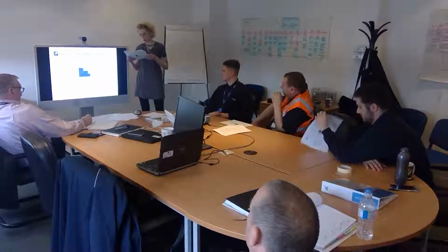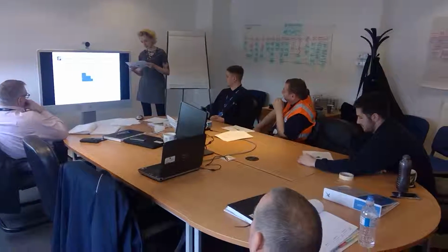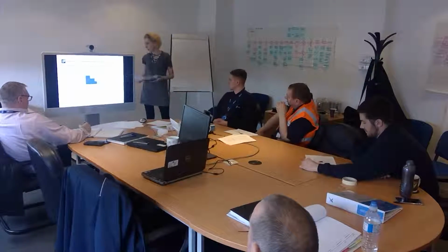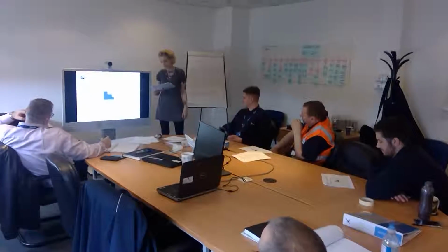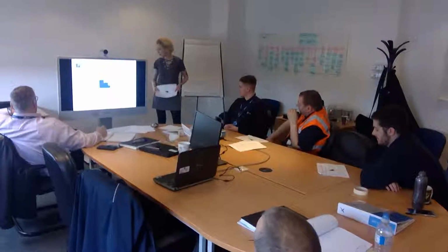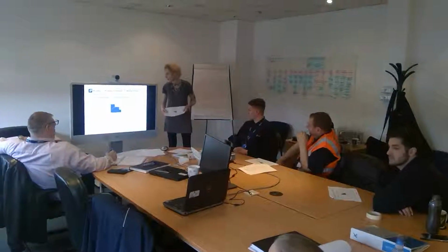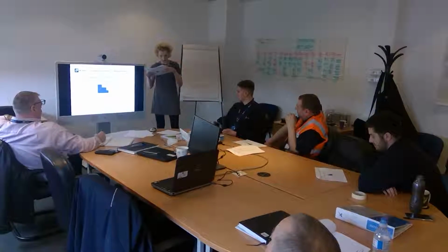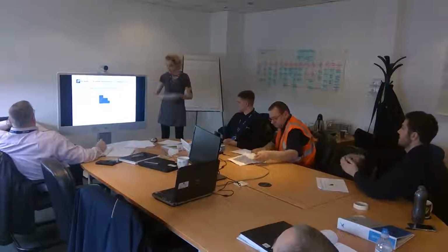And post-production, worst offenders, defects just generally. That's inspectors knocking things back if there's undercut on welds or whatever welding defects, they bounce them back for welders to redo those. A lot of the time that's just human error, something gone wrong with the welding. Second one, dispatch without inspection. Mine's misprinted that, amazing.